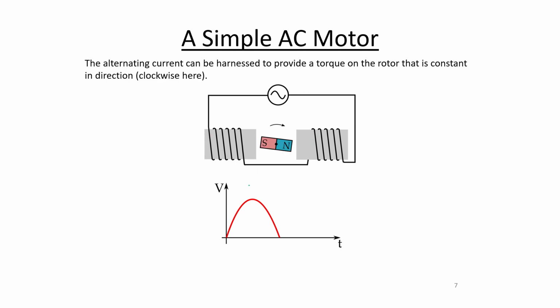And so when we come to the point where the voltage has gone away for an instant, right, we're right here on the axis, so voltage is 0, so current is 0, so there are no poles on the electromagnets. And at this point, I guess the rotor would just sort of be coasting, but it has this clockwise rotation. It will have felt forces to cause it to have a rotational velocity in this direction. All right. So we can play a couple more frames.